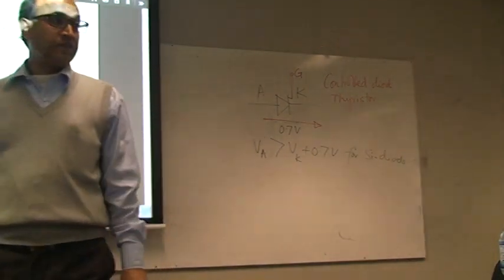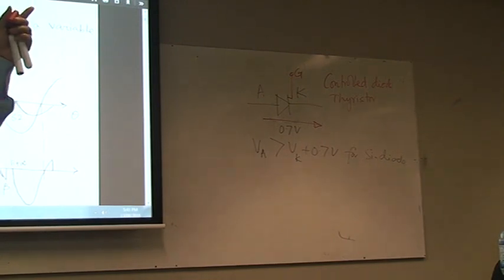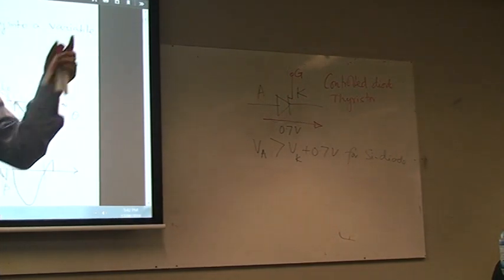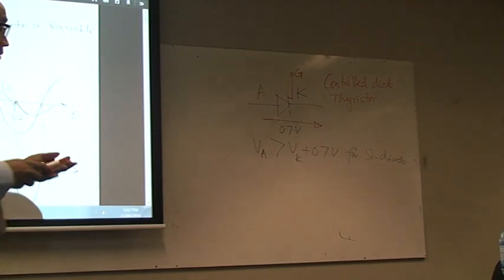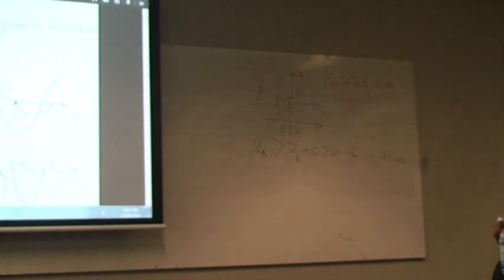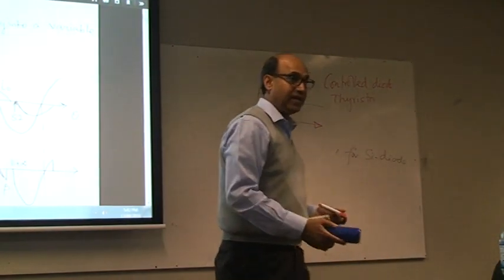So it's a bit like a one-directional transistor. It is a one-directional diode, but one-directional controller. So if you use this type of device, you can actually control DC, isn't it? You cannot control alternating current, because alternating current means you need to allow the current to flow in both directions. So what you usually do is have another thyristor, anti-parallel.